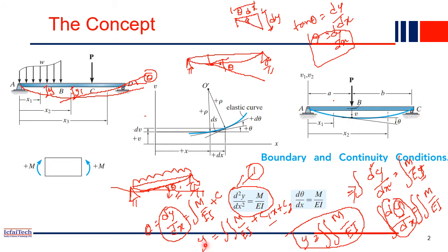So y equal to, y means deflection at A, equal to 0, right? So this y value should be equal to 0 when x value is also 0. So x is a variable starting from here. So here x equal to 0 and here x equal to the total length of the beam. Maybe it is L, right? So when x equal to 0, you have y equal to 0. So from here, you get one equation, and another equation from here you